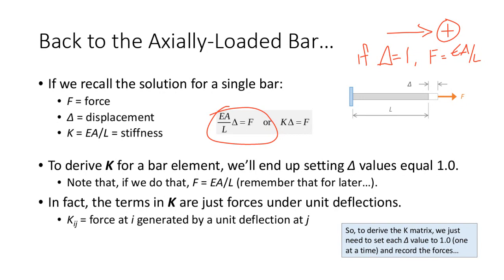That's a great question. The short answer is yes, because of the way that we describe local versus global coordinates, and the transformation between local and global coordinates will make a whole lot more sense on Monday. Let me put it like this. When you run an analysis in RISA, RISA doesn't know what you have defined in terms of a local coordinate system. Here's your problem, here's 0, 0, and you're putting the truss wherever. Everything's with respect to that common origin, right? Now, for a given member, you could have the coordinate system facing one way or the other.